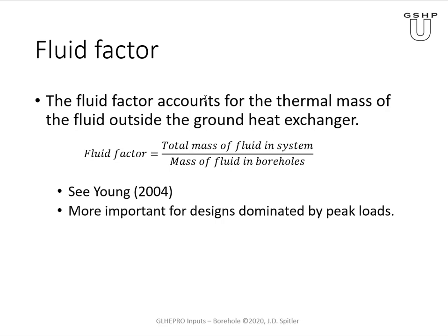I've done some calculations for some systems, looking at where the heat pumps are in the building, and we're talking about systems with distributed heat pumps, and I found it wasn't unusual to have the same amount of fluid outside the borehole and in the rest of the piping as you have inside the borehole. So if you double that, you'll decrease this peak temperature rise, particularly if the peak is short.